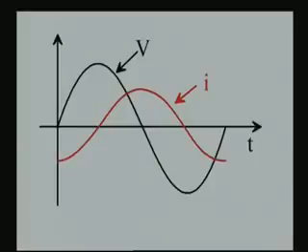What do you see? What is the difference between the previous voltage wave shape in the case of the resistive load and that of now with the inductive load? You see that the current lags the voltage. The current crosses the 0 and goes positive much later than the voltage wave shape, which started going positive, crossing 0 right at the origin. So, basically we see that in the case of the inductive circuit, the current is lagging the voltage.